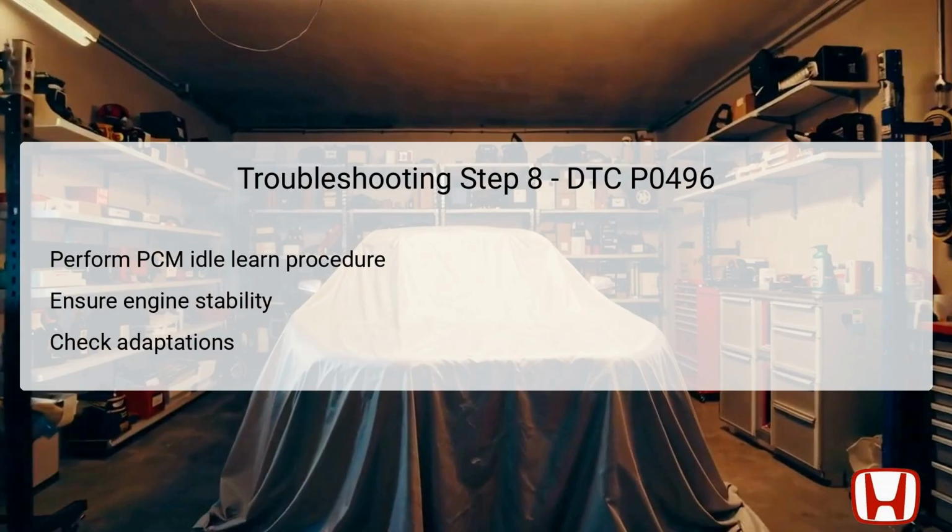This step is necessary to allow the control module to adjust its learned values and calibrate the engine's idle settings post-repair. By doing this, the system can adapt to any changes made during the valve replacement and ensure smooth engine operation. The idle learn procedure is critical for engine stability, allowing for optimal functioning of the vehicle under various conditions.